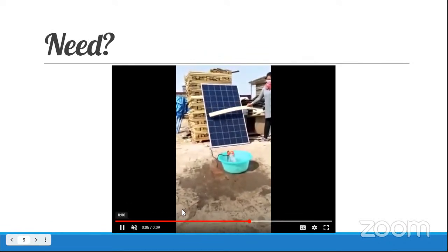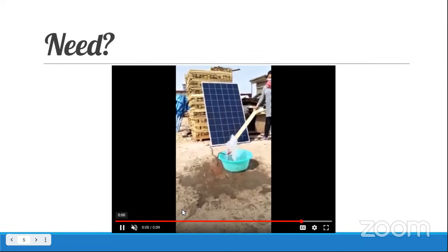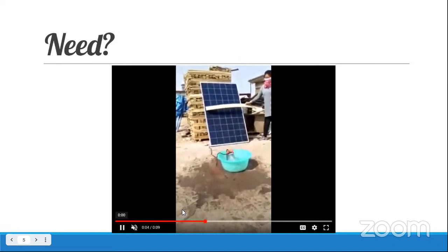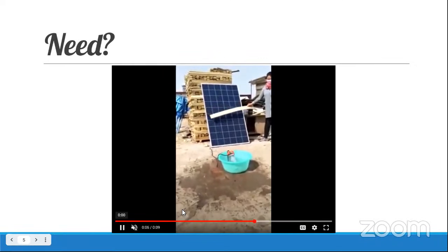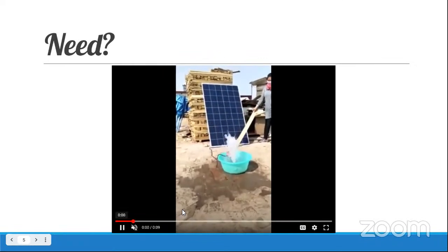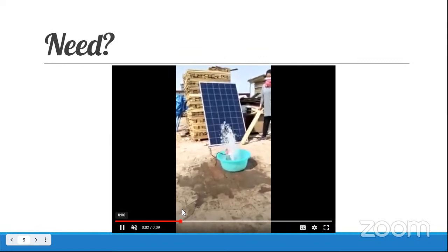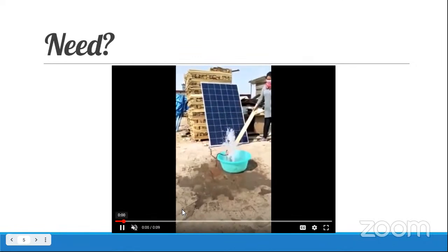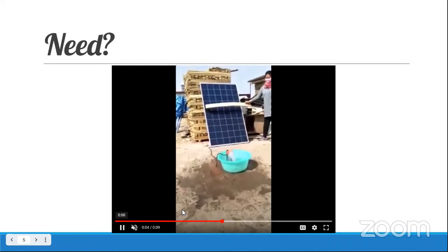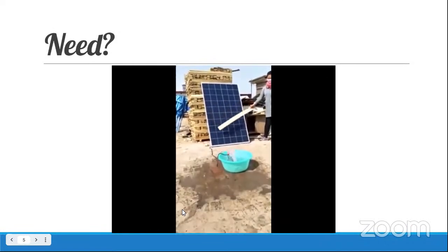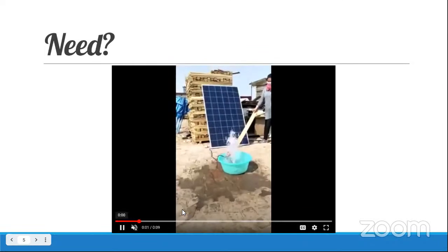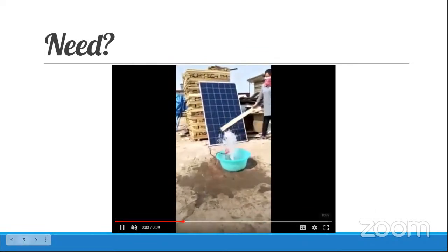I think this video is enough to show how important operation and maintenance is. If a plant is lying with dust, pollen, tree pollen, flower pollen, etc. residing on the panel, then it can reduce the production and can hamper the payback period, the financials, and many other things for the asset owners. Reaching the next slide,